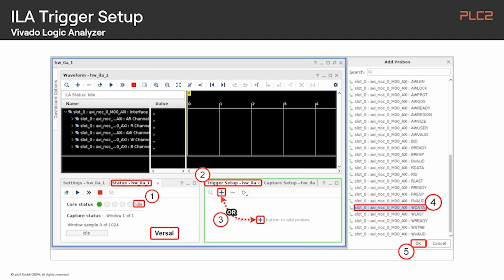Okay, so actually, if you like, you can, for example, give it a try, click here, force a trigger, and then it should directly bring in new signals. And as far as this works, you can then define a customizable trigger. And this will start from the plus icon, and you see those probe signals which are enabled and which are wired up in your hardware project.